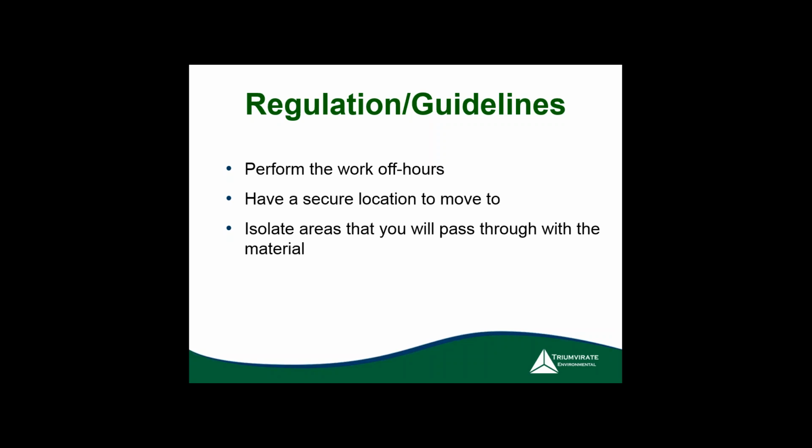And then we'll isolate all the areas that are going to be affected as we move the material through the building. That can be blocking off hallways, elevators, parts of buildings, just to get the material out the door, and then having a secure location. We don't have to worry about delivery trucks or foot traffic or any cars coming in. As a rule of thumb, that's the best way that we manage the material.